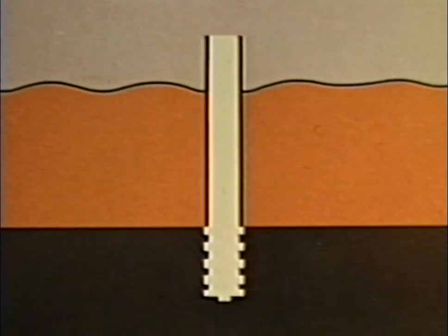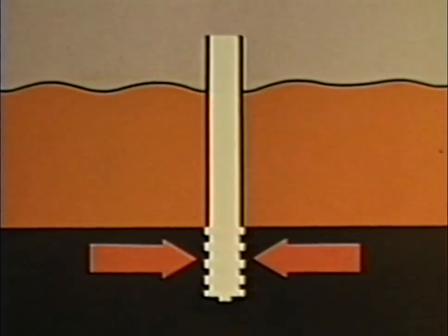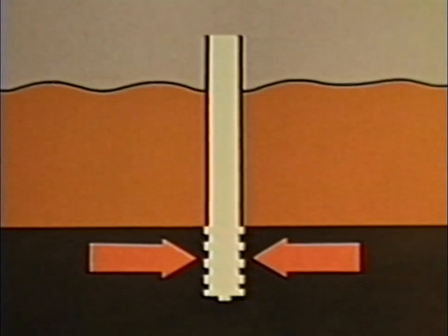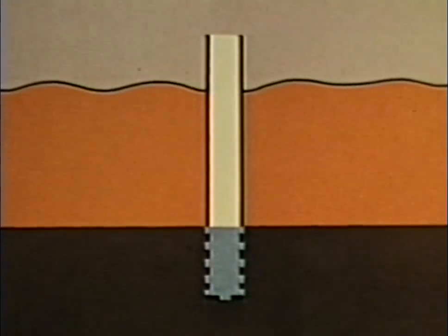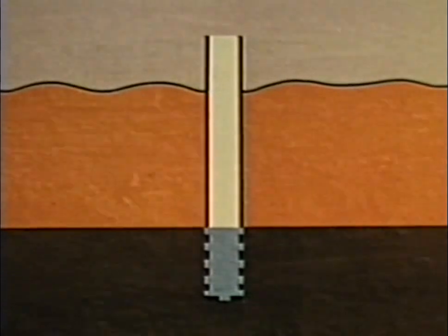When a shallow observation well is installed below the water table in clay deposits, the well will initially have no water. Gradually, water in the clay will seep into the well bore. And eventually, the water level in the well will have a level that is the same as that of the natural water table.